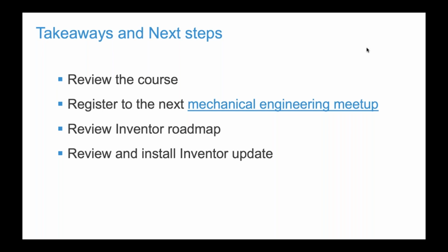Yeah, that makes sense. So again, two solutions: either the sub-div modeling in Inventor or Fusion, or you can still use third-party formats such as SAT or OBJ to import to Inventor.